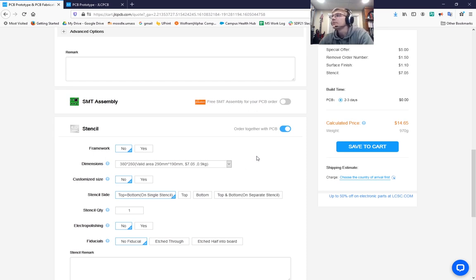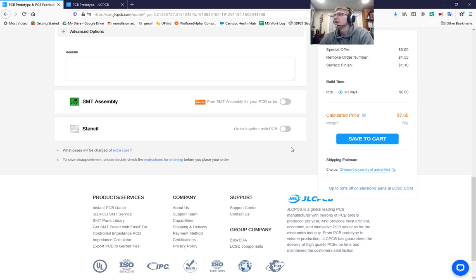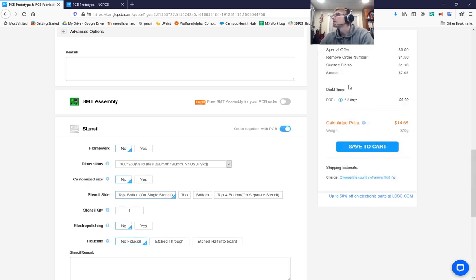If you have small chips and small parts, this is a pretty great option, and I think I would actually strongly recommend it for anyone. If you're using a QFN package on your board, you're going to need this. So strongly consider whether or not you'll need a stencil. Feel free to consult with M5 staff and ask them if they think that's a good idea. If you have a board that's pretty big and it has one TQFP package on it, we can probably hand solder that, and you don't need to spend the money on a stencil. You can see that the stencil by itself costs more than all of the PCBs.